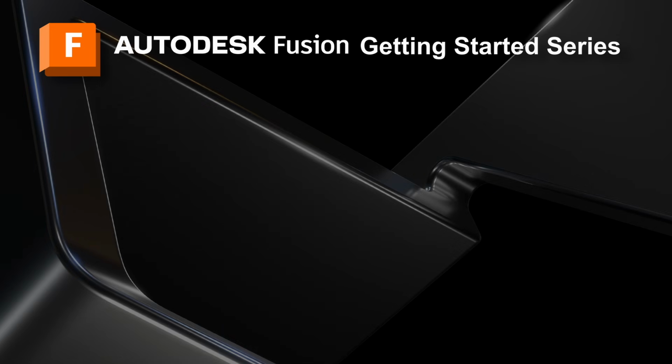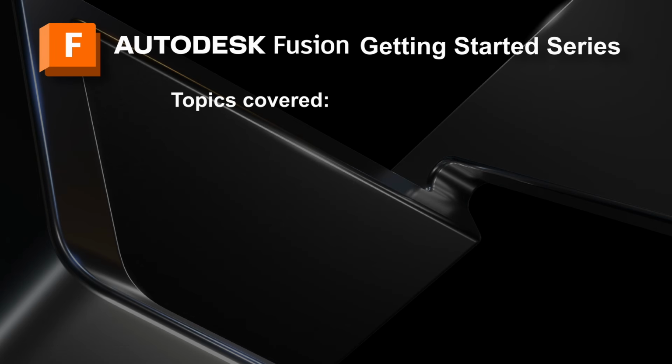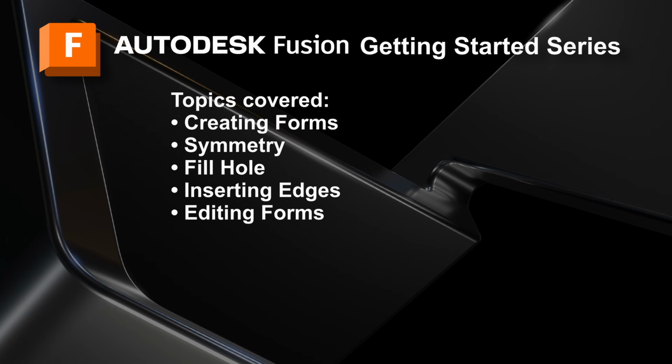In this video, the 10th in the Getting Started series, we will learn about the form command to create the handle grip and learn some additional functionality such as creating forms, using symmetry, fill hole, inserting edges, editing forms, and extend to adjacent faces.